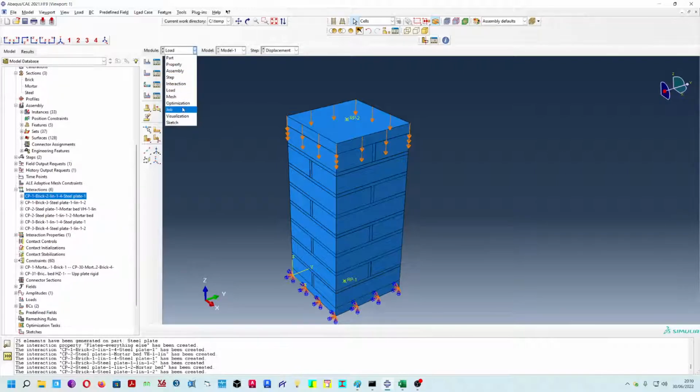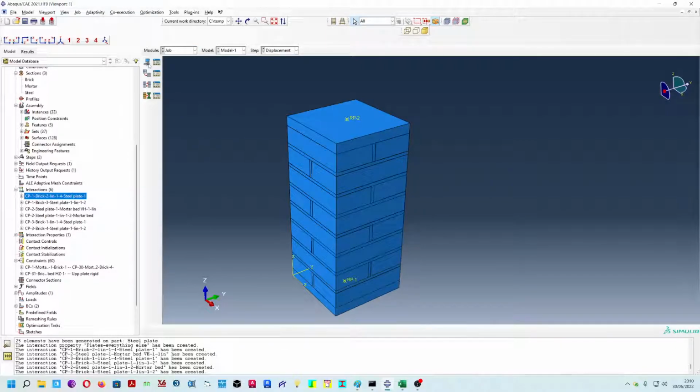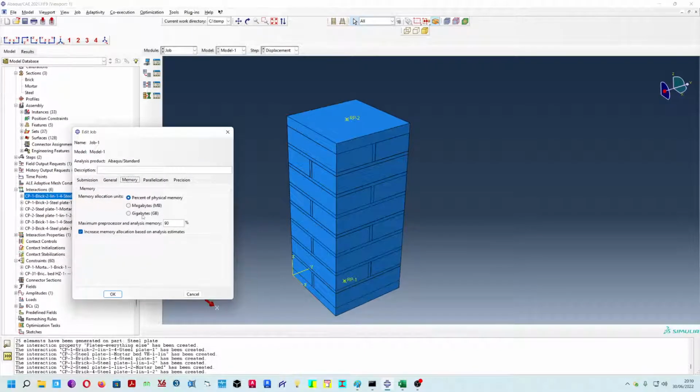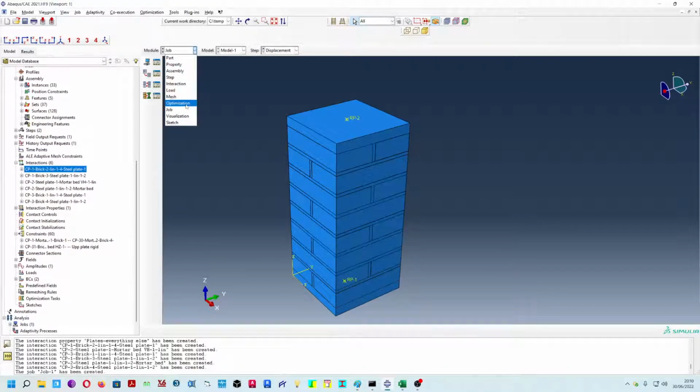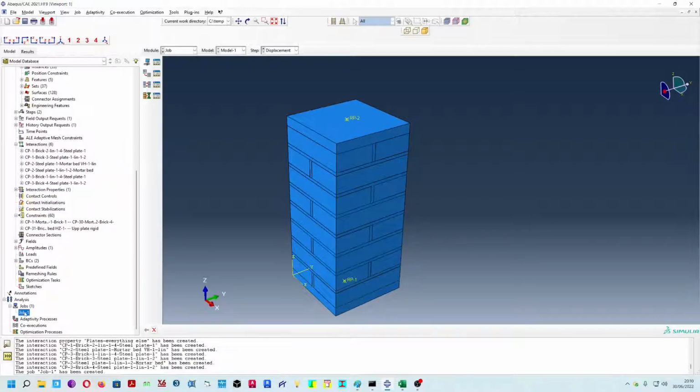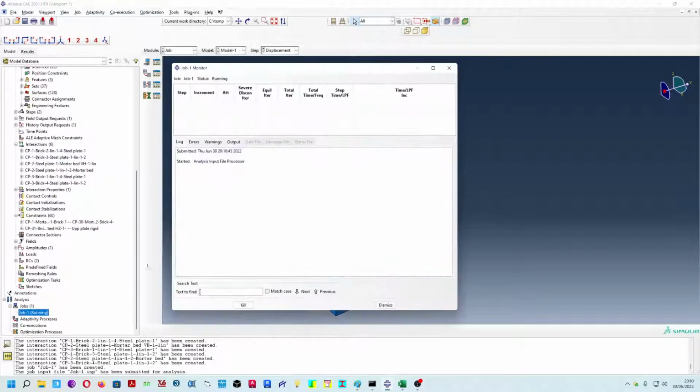Now, we have done everything, I suppose. Let's go with the job. Create a job. Job 1, source model, continue. I'm going to put some gigs in it. Let's say 26 gigs, multiple processors, 8, and then we can run the job. Let's run the job, submit. Okay. Monitor.